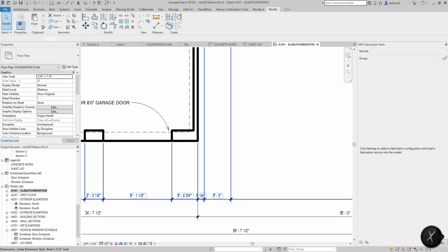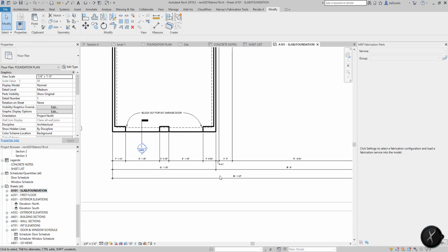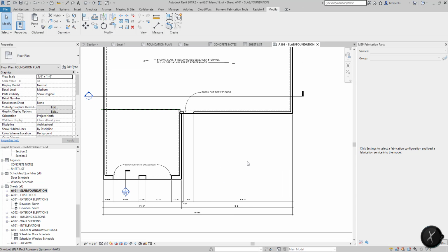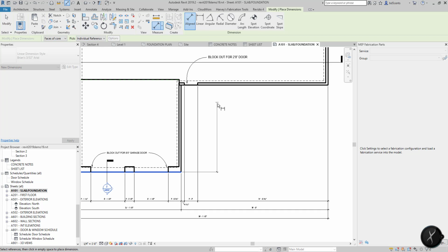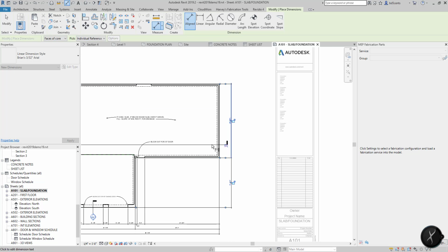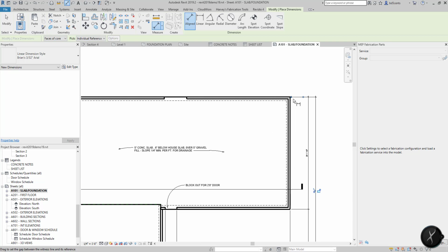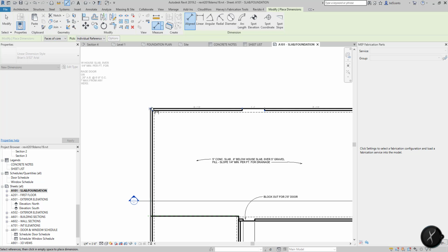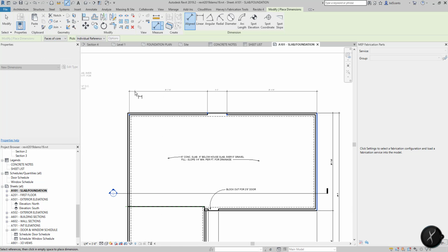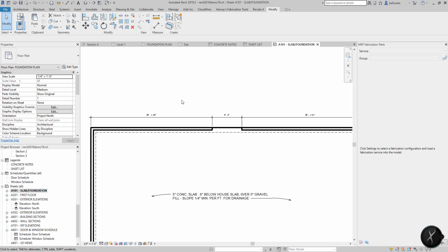Now, this gets a little dicey, so you can pull this out to clean it up, and the dimensioning makes it really easy. All I did was hit DI and started dimensioning to the lines. And so I'm going to do those overalls and this overall, and it snaps. And we're going to dimension to openings on this north wall. I just selected the wrong one, but I'll show you how we can fix that right now. I can select this and drag to the outside, and it'll update.